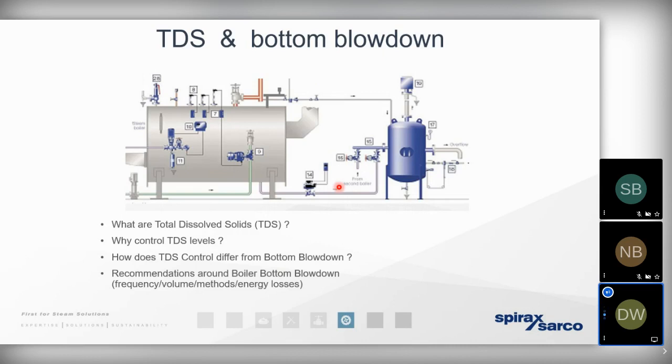And that's what can contribute to that rich foaming layer that we experience in a boiler when we get a high chemical composition. Any fluctuation in boiler pressure can result in that foaming layer expanding and being drawn out into the distribution pipework. So that foam will be very wet and sticky, and that will contribute to the erosion, corrosion, and water hammer, steam with very little energy contained within it. We also know that that foam will dry out as scale, and that scale can not only result in further erosion as it passes around the network, but it can bind itself to sensitive heat transfer surface areas, such as sterilizers or plate heat exchangers. And that can result in an insulating layer or a barrier to heat transfer.